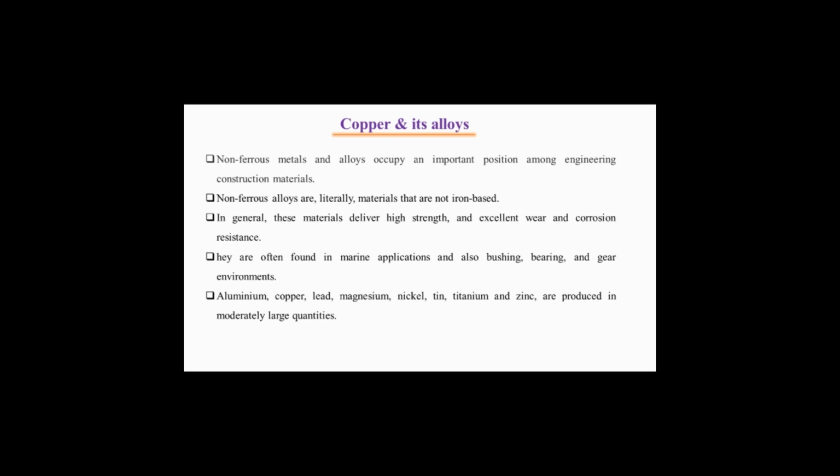Copper is a material which has excellent electrical conductivity, and it is ductile, malleable, soft, and has good machinability. Some of the common non-ferrous metals are aluminum, copper, lead, magnesium, nickel, tin, titanium and zinc. Non-ferrous alloys are materials that are not iron based. Non-ferrous metals and alloys occupy an important position amongst engineering construction materials.